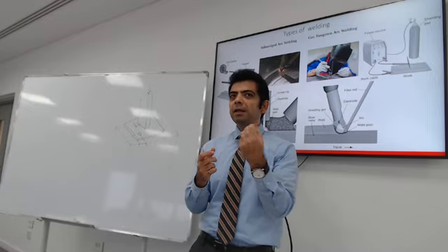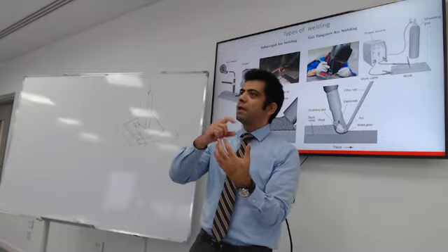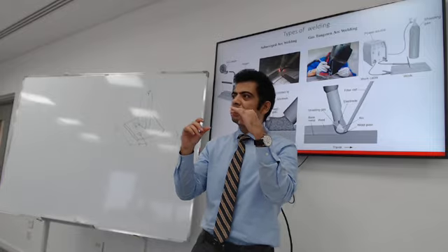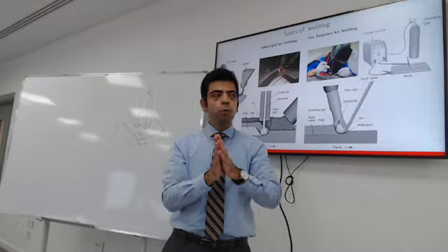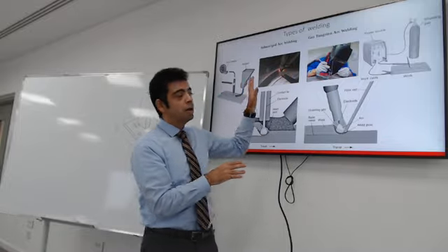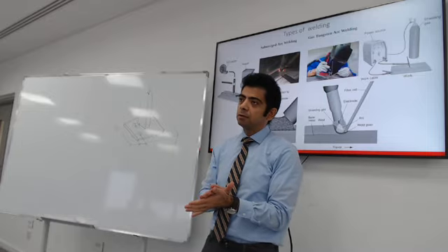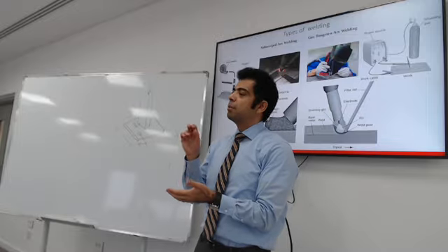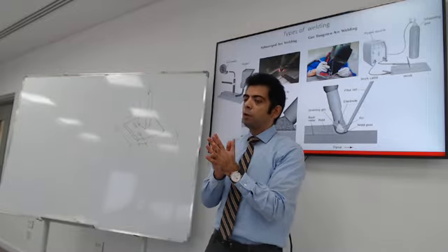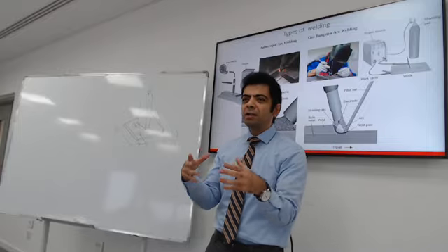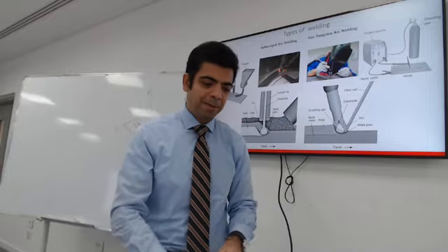And you might want to leave a general note: use electrode with these specifications if you're welding. You don't have to go into too much detail. You probably will leave the responsibility of welding to the contractor. The contractor will provide a professional welder and they will be responsible for the work, but you also want to know what goes into it so that you can design it properly.